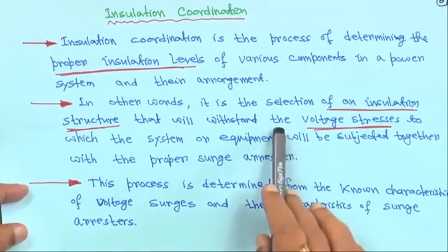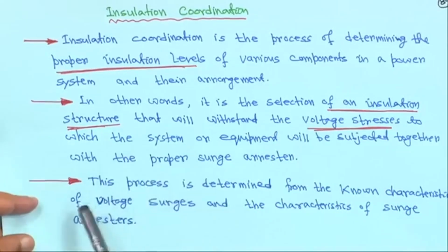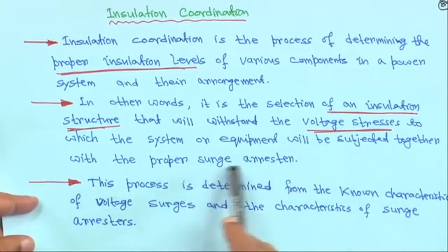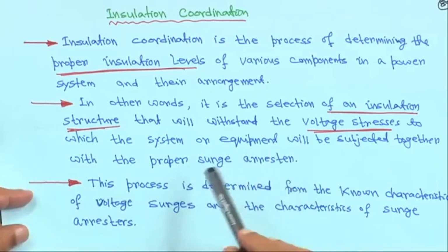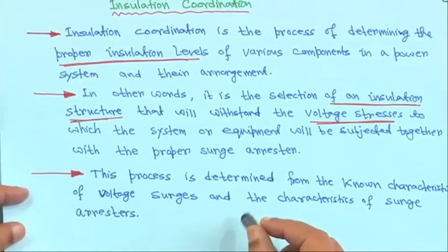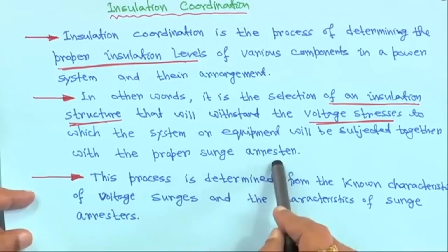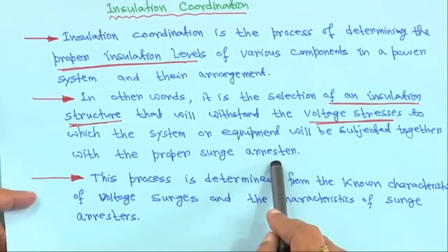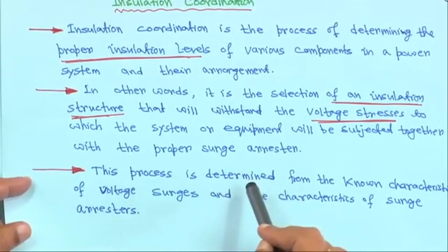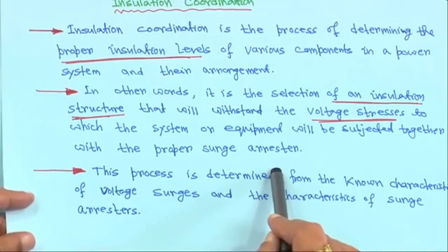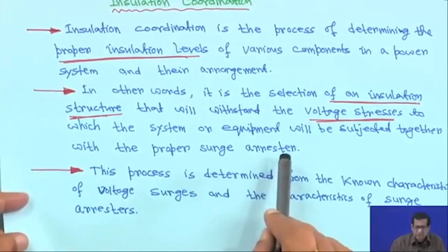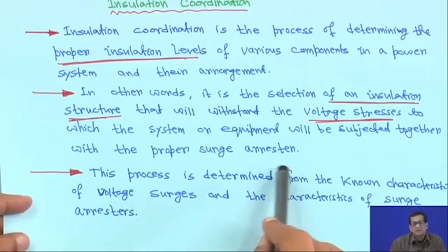That means, particularly this maximum switching or impulse or surge comes due to the lightning stroke. So, that is why the lightning arrestor is designed in such a fashion that it can protect the equipment, and when they design, they consider all the worst cases. Accordingly, the surge arrestor rating will be determined such that it can protect the equipment in, say, a substation.